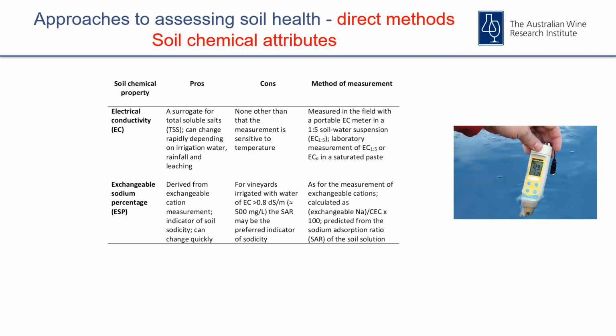But in many cases, you can get an idea of soil permeability from examination of the profile pits in the first place. This is what I like to do, because when you have a profile pit, you can look at the faces of the pit, which should be relatively undisturbed, and you can get an idea of whether you've got a compacted subsoil or not, and whether that might present problems from the point of view of permeability.